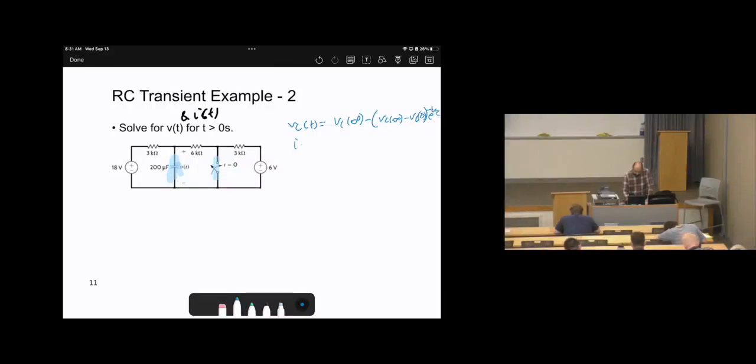To calculate the current, I sub c, when you see c here, I mean sub c, Ic of t equals C times the time derivative of Vc of t, dVc by dt. Now, we have three unknowns: Vc of 0, tau, and Vc of infinity. Therefore, there should be three steps.